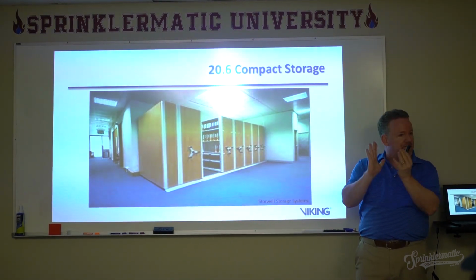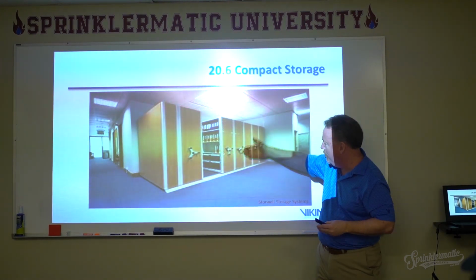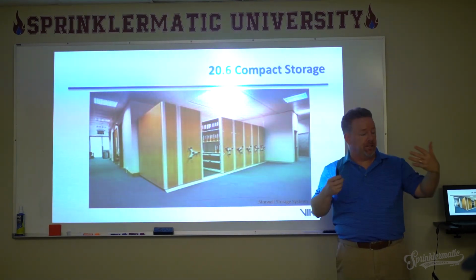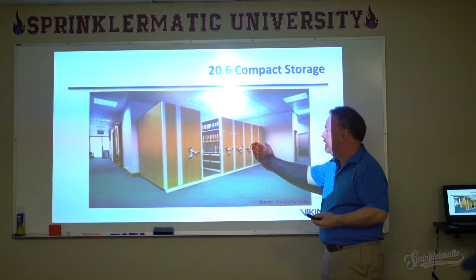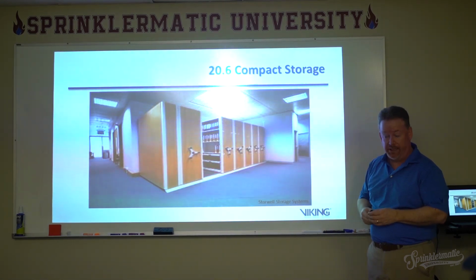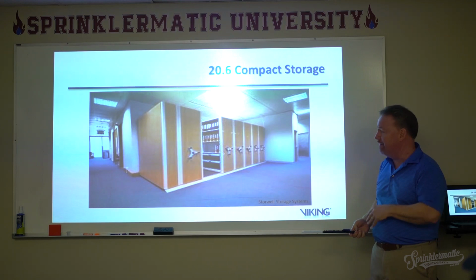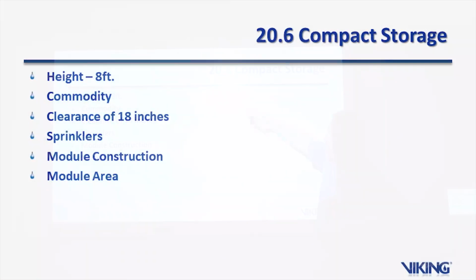No, a lot of times it's so compact together, and because there are no flue spaces in here, what they found was, yeah, actually, if you limit the amount of plastics that can be used in here, if you limit it to files only, then you can protect this kind of a space as long as the height is limited to 8 feet, commodity clearance is 18 inches to the sprinklers. You can use standard spray sprinklers.